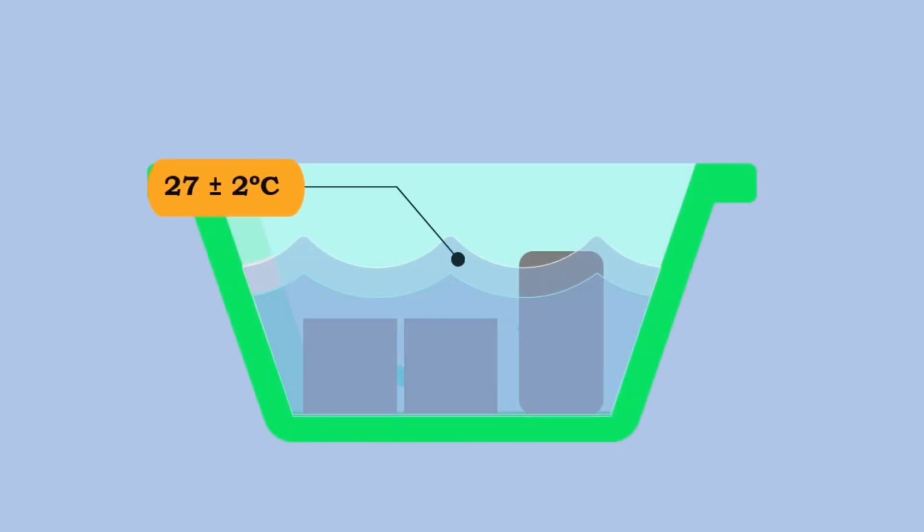After a day, the mold is removed and the specimens are dropped into the curing tank at a standard temperature of 27 plus or minus 2 degrees Celsius.